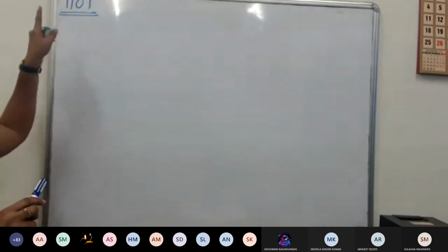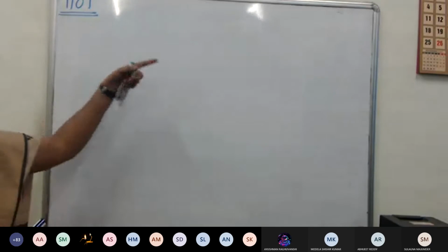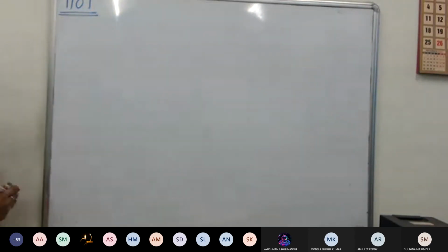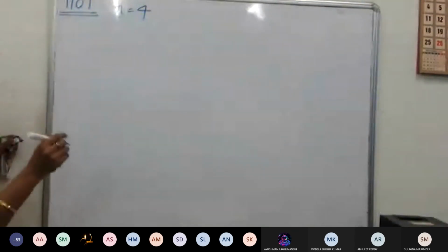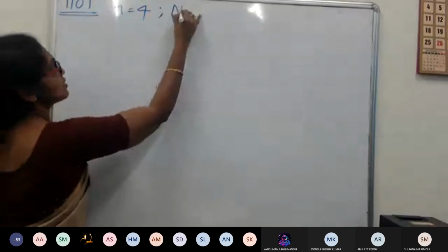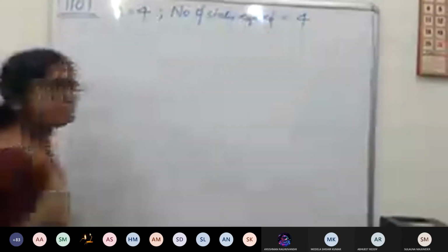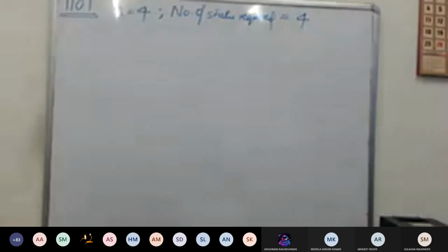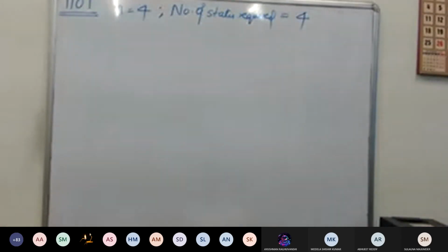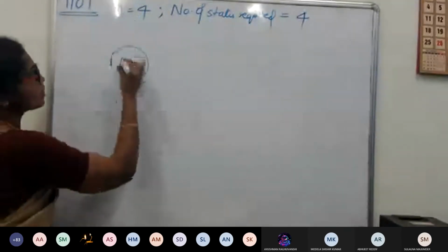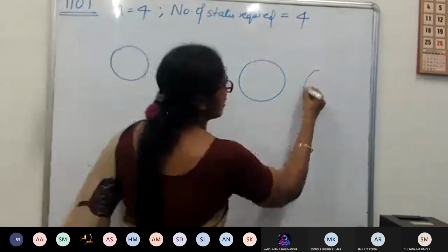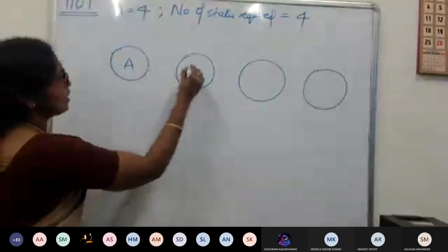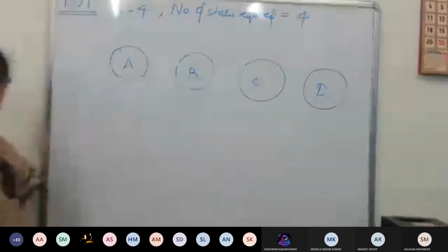So if you have n number of bits, according to the Mealy design, we will have n states. Here the sequence to be detected is 1101, so n equals 4. When n equals 4, the number of states required according to Mealy is 4 states. I don't know what the states are, so I will give some alphabets to them, A, B, C, D. So I will use 4 states, because a state diagram is normally drawn like this, you remember, right? State diagrams. A, B, C, D. 4 states are required. I don't know the connections.